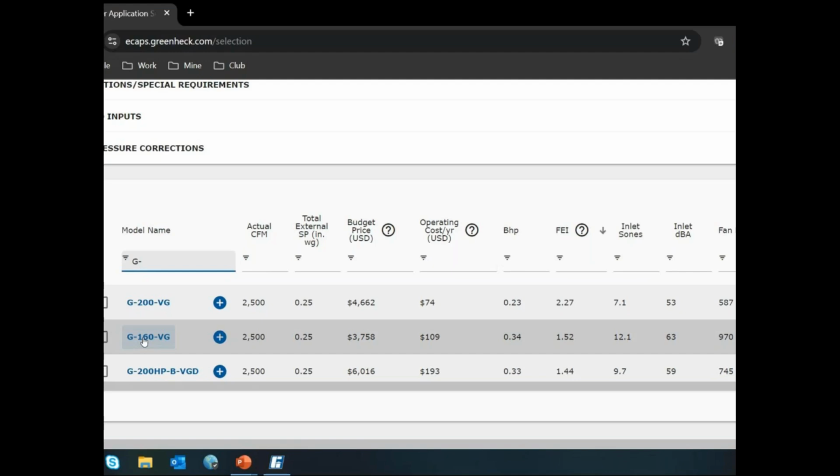Like if I have a high temp airstream, yeah, motors hate heat. Get the motor out of the airstream. Belt drive is perfect for that. If I'm at high horsepower, right? There are reasons out there that belt drive will never go away. But to put numbers behind it, 10 years ago, 80% of my fans sold in power roof ventilators was belt drive. Today, because EC motors are available, VFDs are available, 65 to 70% of my sales now are direct drive. So the entire industry in the last 10 years has completely flipped.